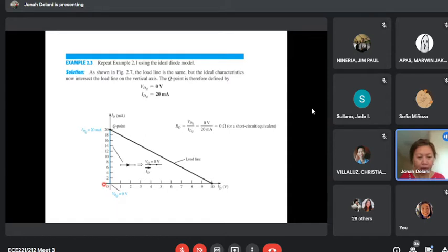So for forward bias, this is the characteristic curve of the diode. If it is on, it is like a switch. There is no voltage drop across the diode. See? Now VD is 0 here. And then, if it is reverse biased, it is exactly 0. There is no leakage current. So for the ideal model, the voltage drop across the diode when forward biased is 0. It is like a switch. It is ideal, no resistance at all. So it is 0 when on. A short circuit would have 0 voltage across it, but very large current.